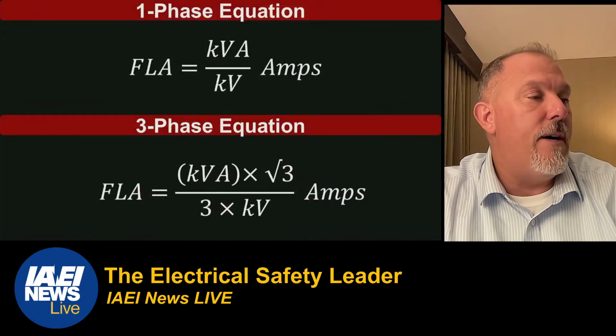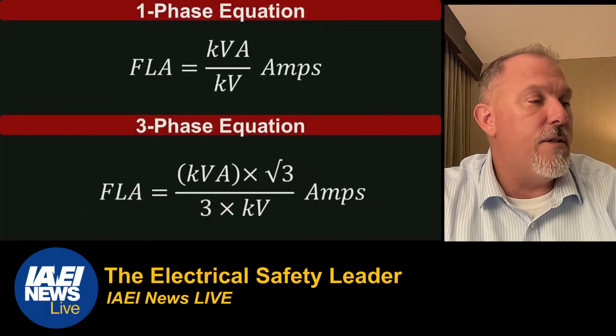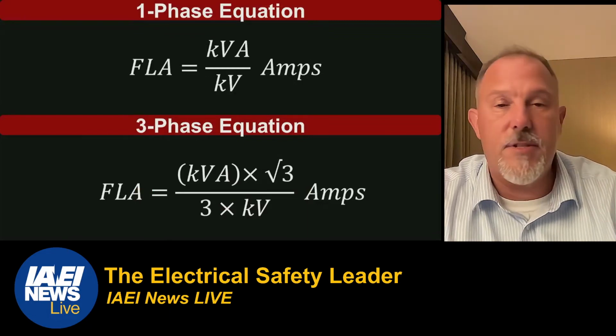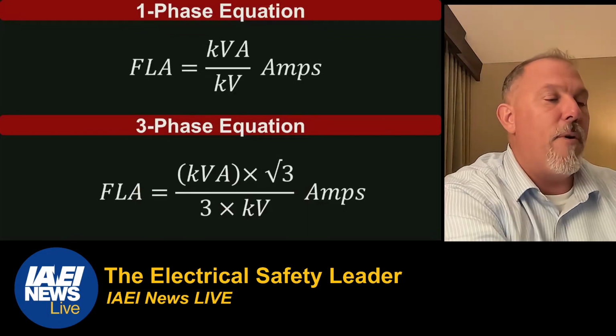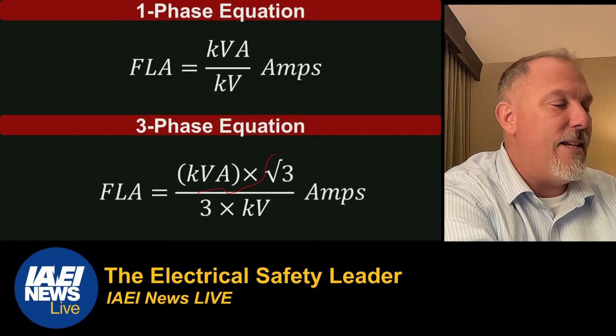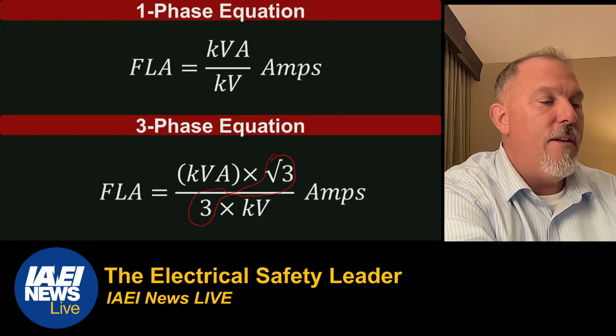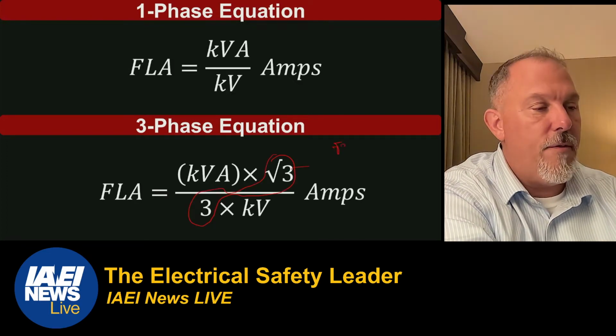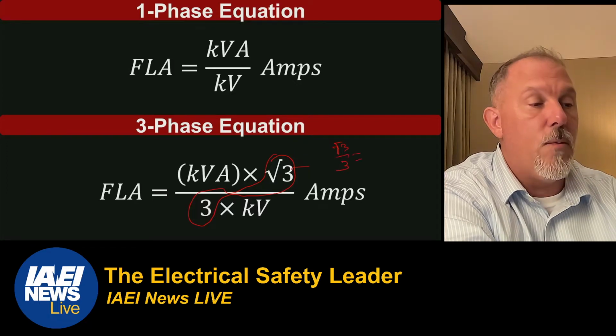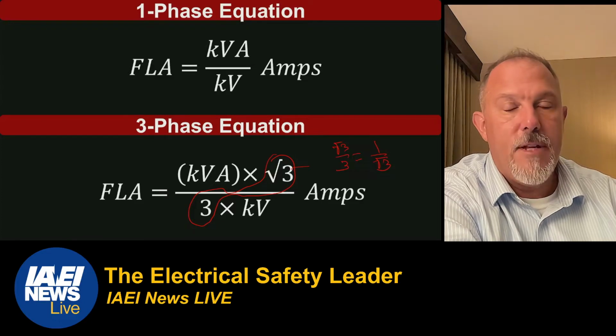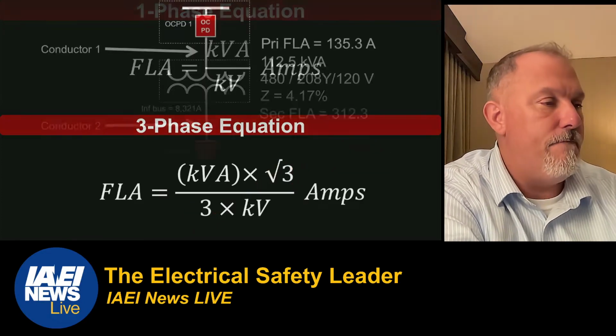I have single phase equations. These are my equations for full load amps I just gave you. And remember, this here, if you do the math, square root of 3 over 3 equals 1 over the square root of 3. So just be mindful of that.